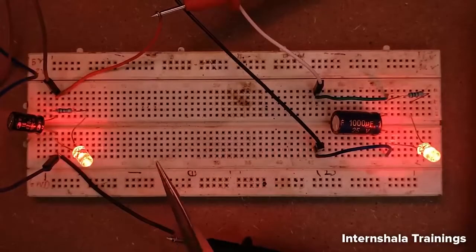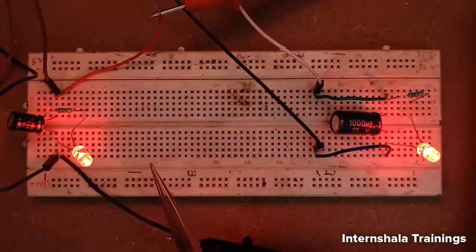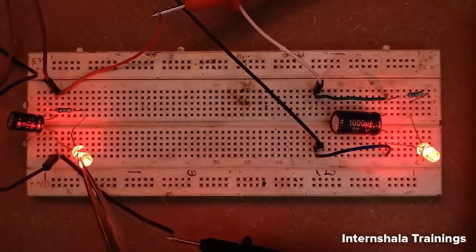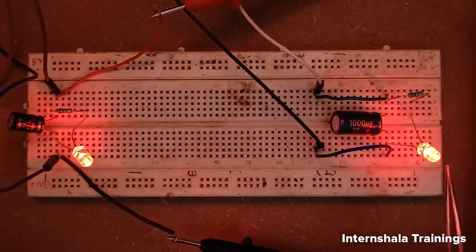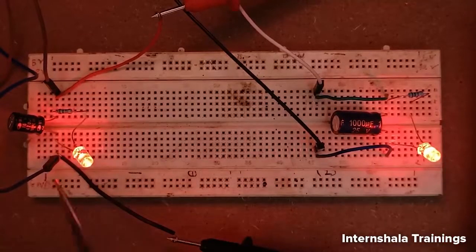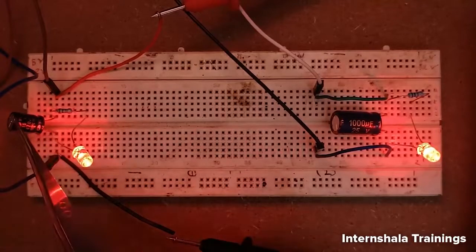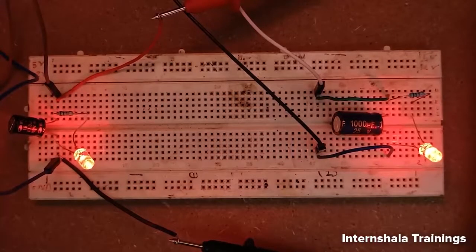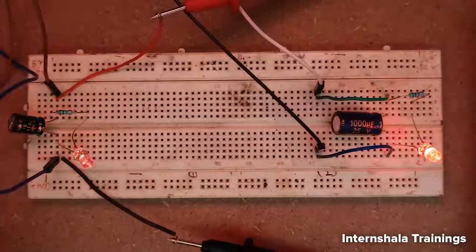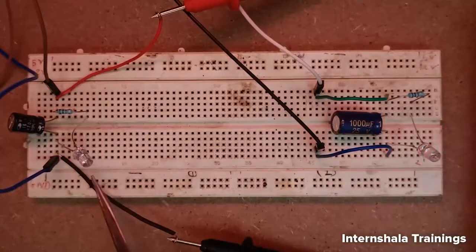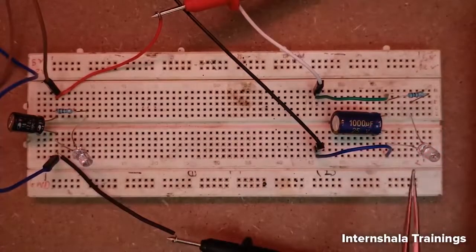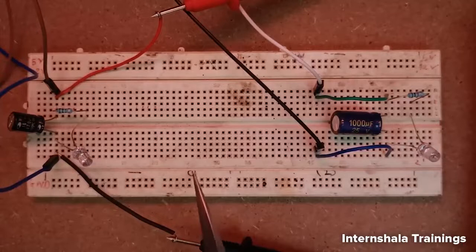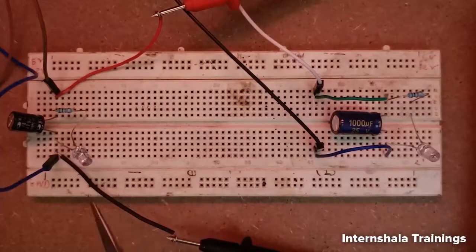I will now switch off the lab bench power supply, and after switching it off, you will observe that this LED switches off early, and after some duration this other LED switches off, because we have connected two different capacitor values. This one is 470 microfarad and this one is 1000 microfarad. Now I will switch off the power supply and let's observe the change. You can see this LED switched off first, and later this LED switched off. That's the demonstration for the energy storage of a capacitor.